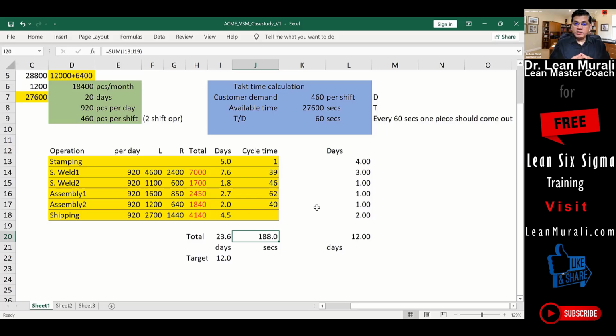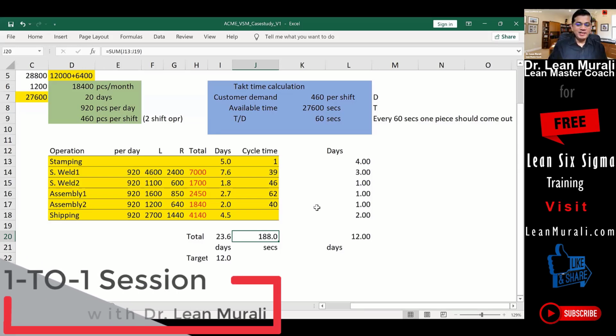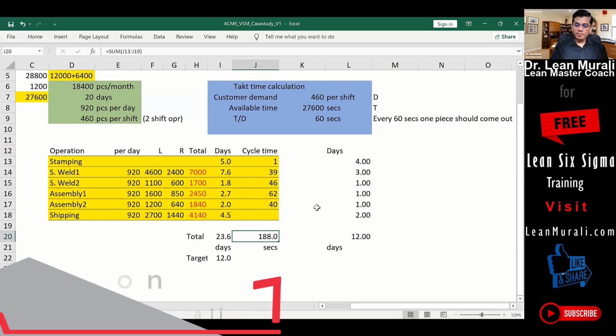If for a particular product you need only 2 or 3 small pieces cut out of that, it will become very difficult. You have to cut the entire sheet because setup time itself is very high. The technology has a limitation in cutting small pieces, or even the supplier has a limitation in giving small sheets. It may not be commercially viable or practically possible to give.